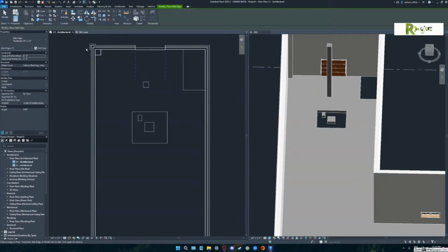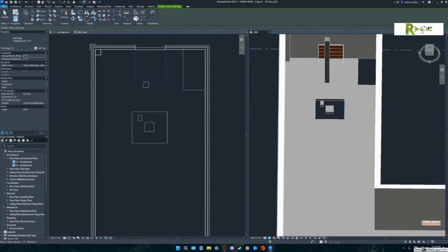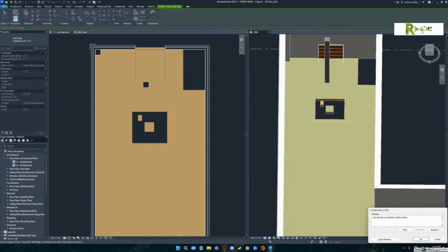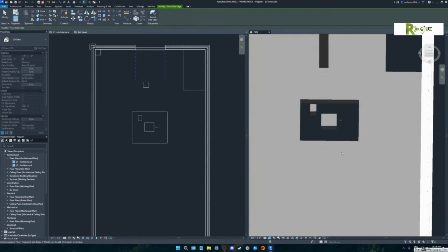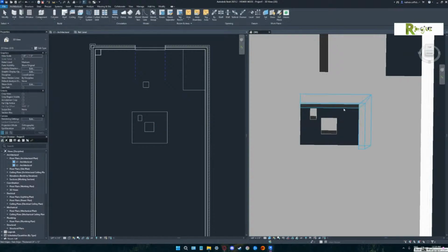All right, pick that. Now, in your 3D view, go pick a couple of the edges of that hole that you carved in there. Yep. Roller wheel, and then there you go. Pick two of those edges. That's fine. You can say okay. Doesn't matter which one. That's fine. You're good. How many do I pick? You're good with that. Now hit escape two times.